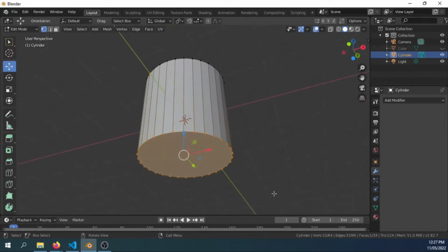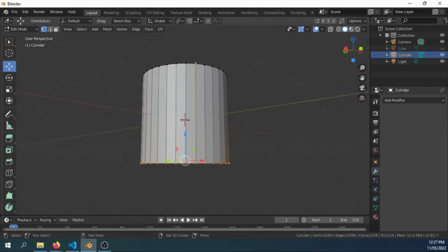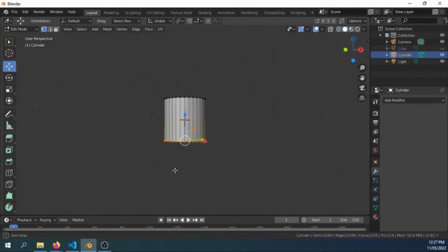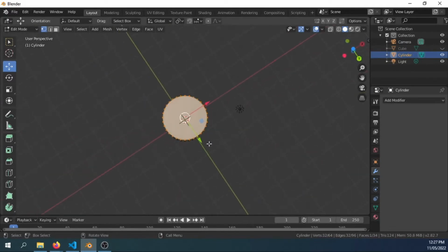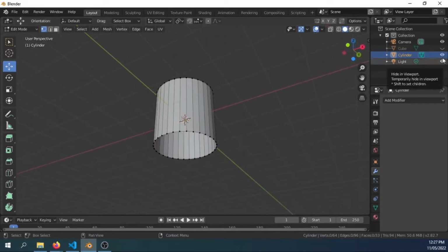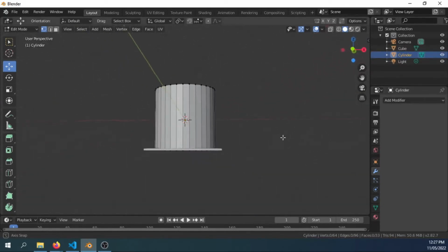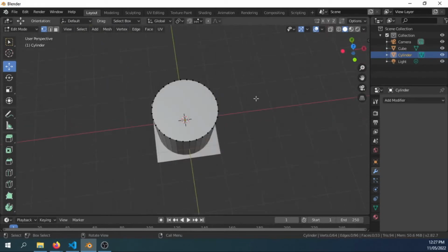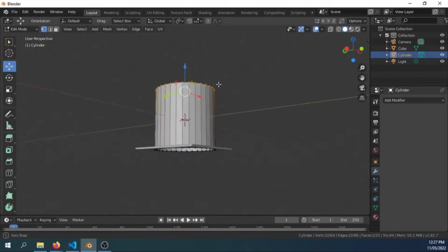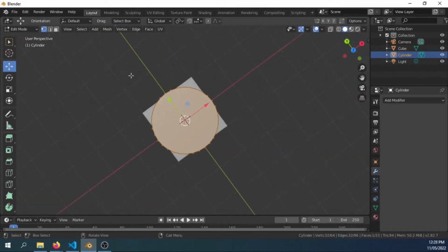Let's first select all of those, and we can see that there's this node from the top, so let's try to remove that. Okay, then X faces. Then let's have the cube. Then let's select the top area here. Make sure that no part of the bottom vertices are selected.